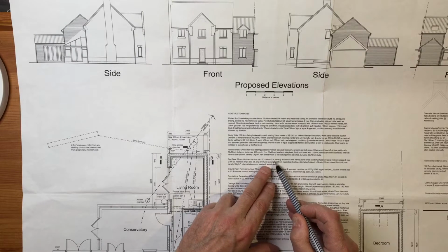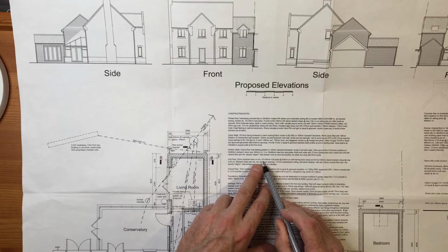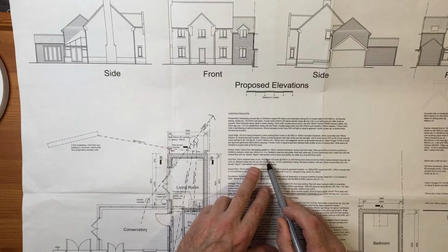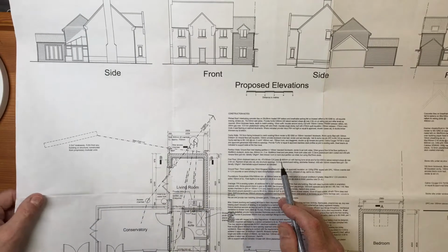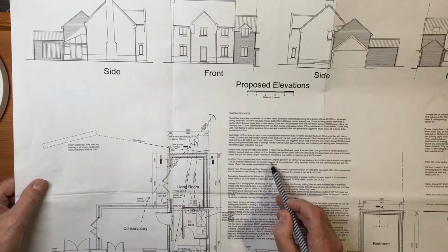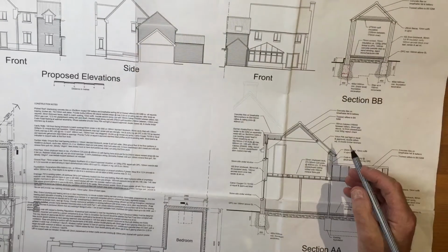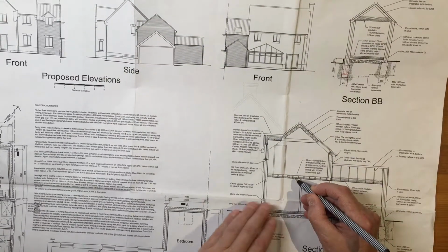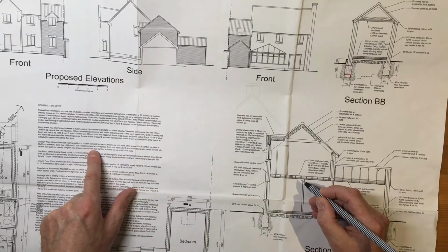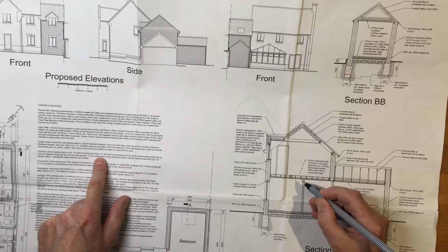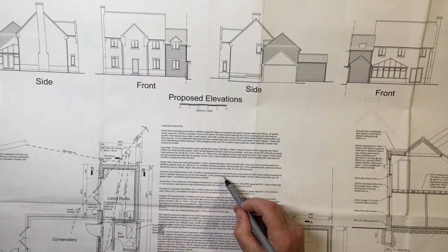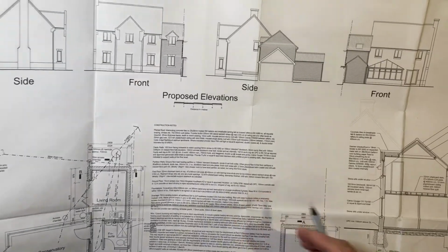It's a structural joist, and it's 47 millimeters by 195 millimeters deep. Okay, that's a section of the floor joist. So that dimension there, the specification they call that, relates to these joists, and it talks about it being 400 millimeters apart somewhere. Yes, 400 millimeters from centre to centre, C straight C.